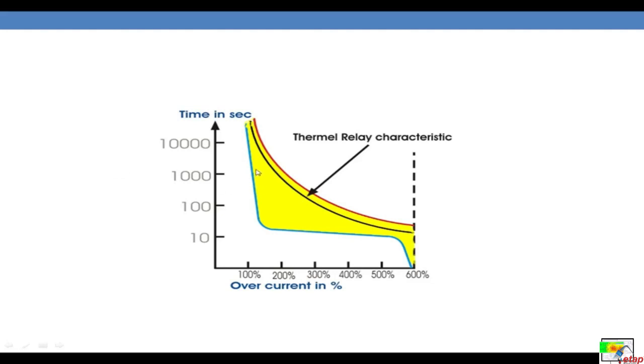When the motor becomes overloaded, the motor could actually sustain a certain amount of overloading, and if that amount of overloading exceeds the threshold value, you actually need to stop the motor or protect the motor from further overloading and prevent the thermal breakdown of the motor. So let us go to ETAP and see how we can implement motor protection.